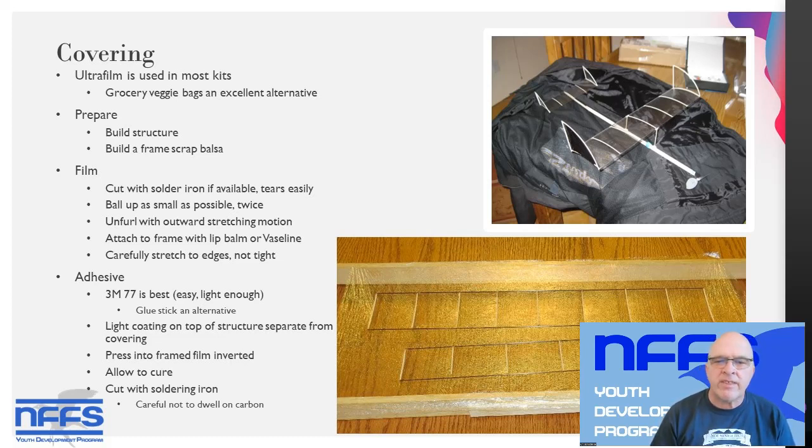Then we take the covering and we ball it up as tight as you can possibly do. The covering for this whole plane will probably end up between the size of a pea and the size of a marble when you squeeze it all up. Carefully unfurl it with a stretching motion. Don't pull it. Comb it with your fingers. Then ball it up again, unfurl it again.